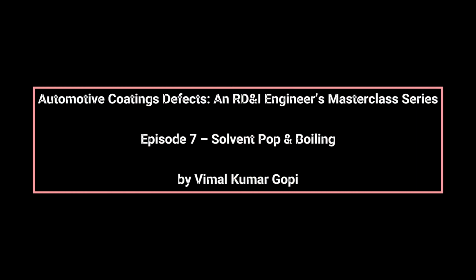Solvent pop and boiling are among the most critical evaporation-driven defects in solvent-borne automotive coatings because they originate silently during film formation and only reveal themselves once damage is irreversible. From an OEM RD&I perspective, these defects are not random events, but predictable outcomes of solvent evaporation imbalance, skin formation, and internal pressure buildup within the coating film.